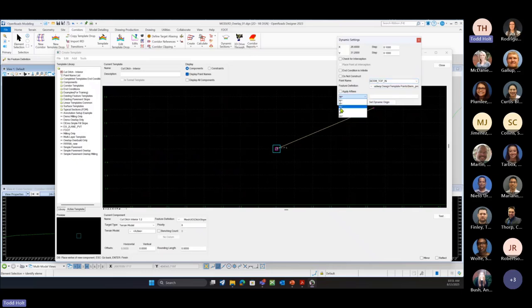We're going to go back to the HS, the horizontal and slope. And we want this to draw for 8 feet. And we'll do a negative 10-degree slope. Because we have our horizontal and slopes, we're going to go 8 feet and a negative 10. And I'm going to hit enter. I'm just going to draw that.